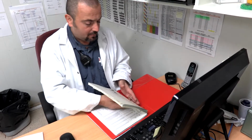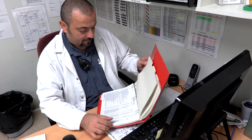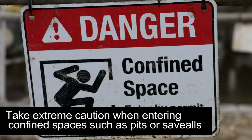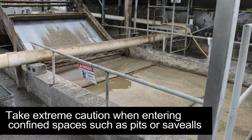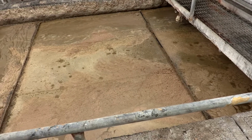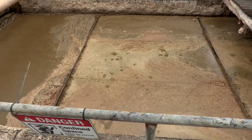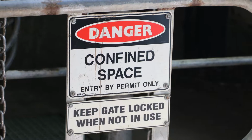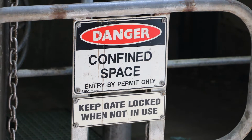There are, however, significant health and safety concerns with upstream processes, mainly related to the risk of confined spaces such as pits and save-alls. Raw wastewater which remains stagnant for long periods may generate potentially toxic levels of hydrogen sulfide. Extreme caution must be exercised in entering such places. Any such activity should comply with confined space regulations.